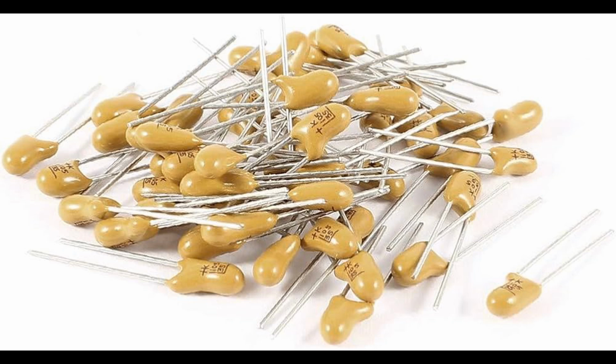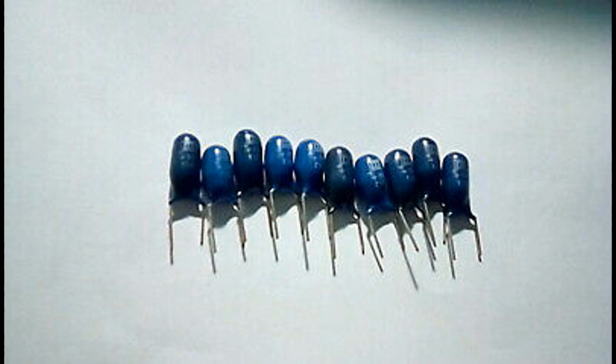6. Capacitive reactance, AC functionality. In AC, alternating current, circuits, capacitors impede the flow of current at different frequencies. Tantalum capacitors, like other capacitors, offer high impedance at low frequencies and low impedance at high frequencies. This makes them suitable for filtering out noise, high-frequency signals, from power supplies and signal lines, as they effectively block DC, direct current, while allowing AC signals to pass.